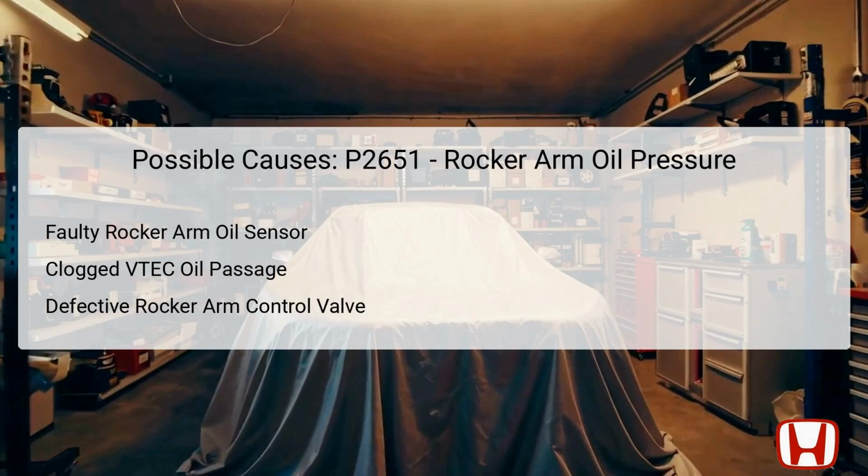The potential causes of DTC P2651 can lead to significant engine performance issues. Firstly, a faulty rocker arm oil pressure sensor might not accurately measure oil pressure, resulting in low output readings to the PCM. Secondly, if there are clogs or debris within the VTEC system oil passage, it can disrupt the oil flow necessary for the rocker arms, preventing them from operating effectively. This could cause the engine to not perform optimally and trigger error codes.